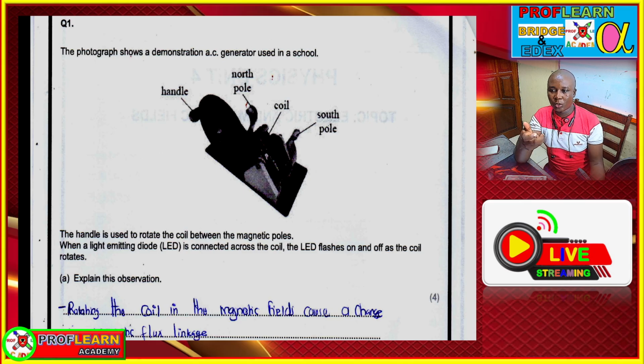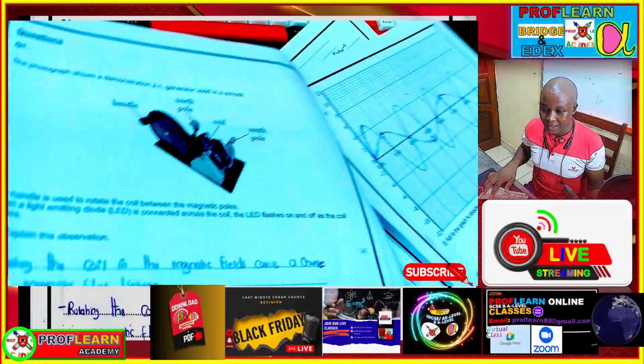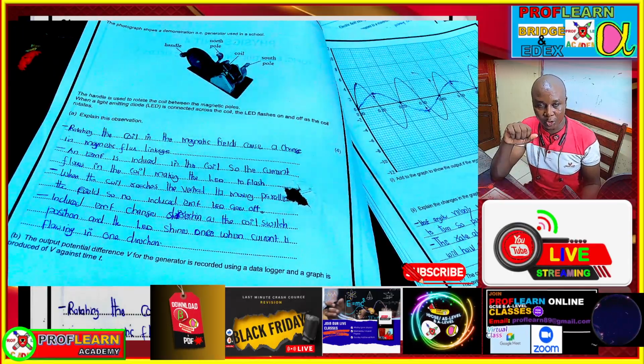So what you need to understand is that when the coil rotates within the magnetic field, the coil is going to cut the magnetic field. And once the coil cuts the magnetic field, there is going to be induced EMF in that particular coil. And every time the coil keeps on changing side within the magnetic field, the current is going to change direction.